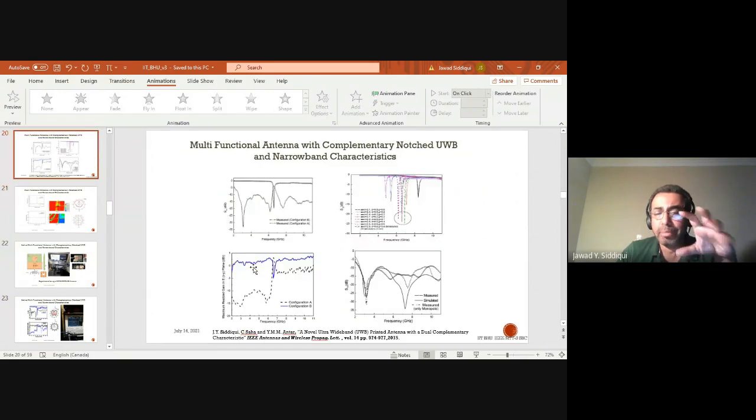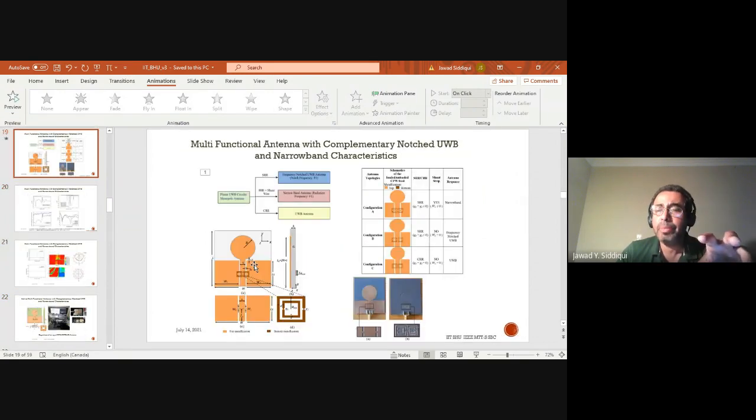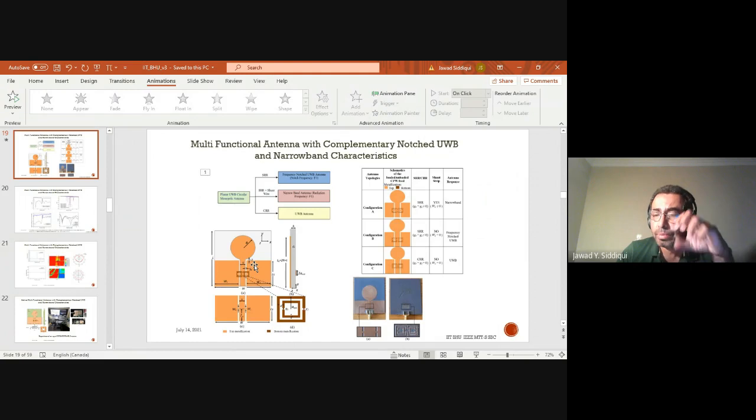And these are not MIMO antennas. The application will be cognitive radio application, where, you know, you require multiple antennas, okay? Multiple antennas in one location will give rise to port coupling, and the proximity for the port isolation becomes an issue. You have multiple ports, the matching becomes an issue.